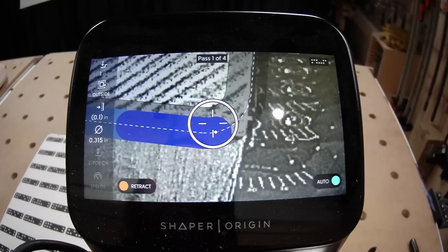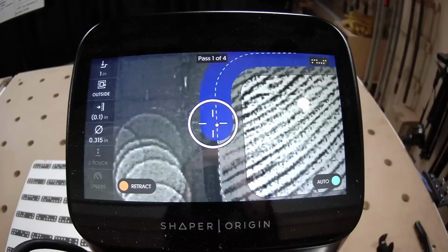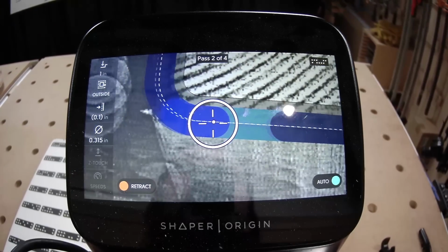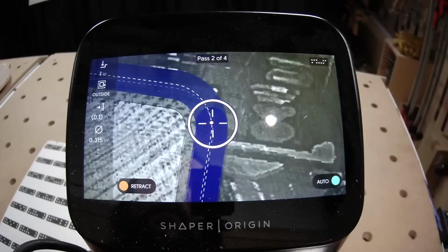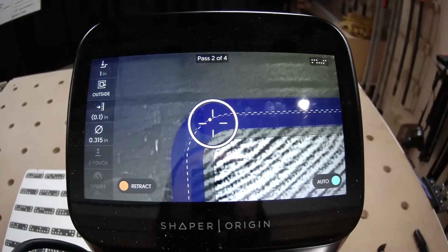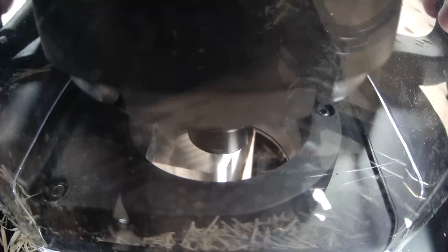So for mortise and tenons, box joints, dovetails, any type of fixturing on rectangular material, I would say probe rectangle is your go-to. Now, the only case where that's not true is if you need to reference a corner or a side, so you could always build that grid afterwards and still get the boundary of that shape.